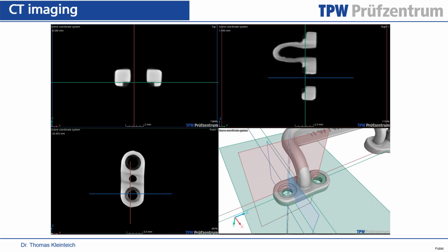It might be caused by foreign material inclusions, by porosity, by cracks, whatsoever. And you can look at the section images at those regions and say, well, okay, here everything looks fine within the resolution limit that I have with the CT system, and I could spend another presentation just talking about this, but within the resolution limit of my system, I cannot detect any porosity, any void, so I think I'm really safe in this position to say there's no material weakness.